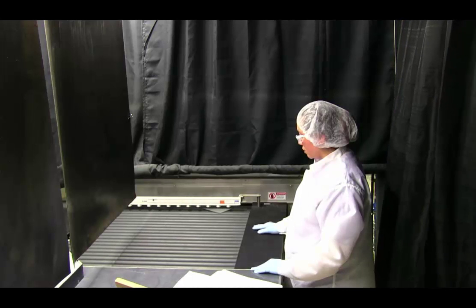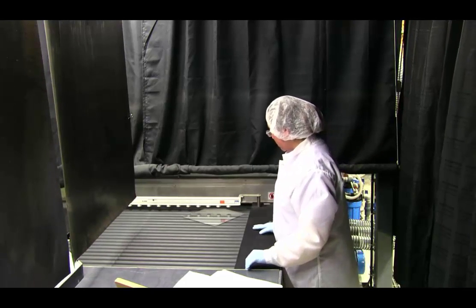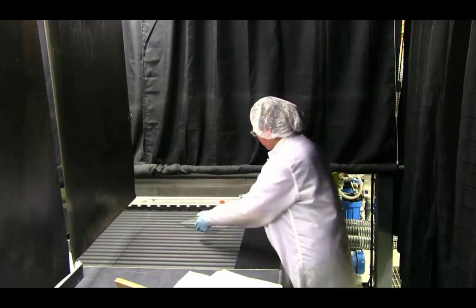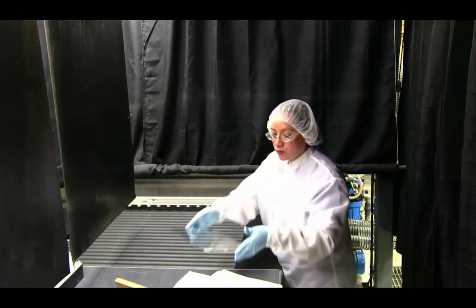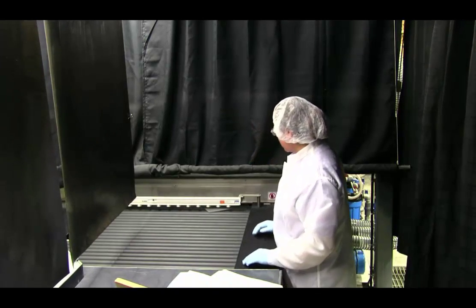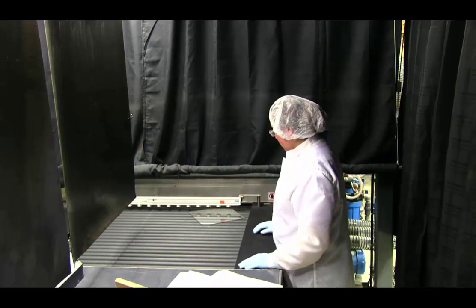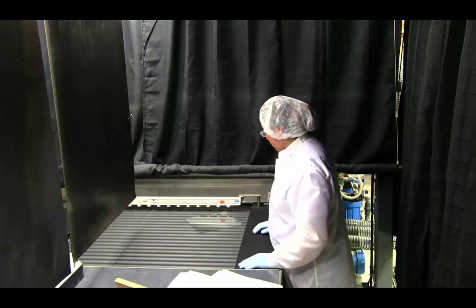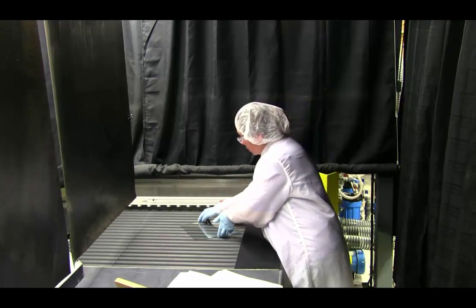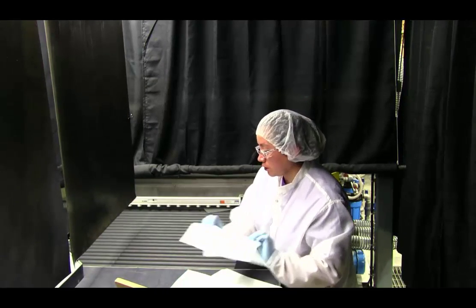Q4 inspection is performed in process in our wash machines or furnaces. As you can see, the part is being conveyed out on the rollers toward the inspector. The entire environment is blacked out with curtains to prevent outside lighting from affecting the inspector's eye during the inspection process. The only source of illumination is an overhead light, not viewed in this video. However, this light source above the glass allows for viewing parts in reflection while on the conveyor.